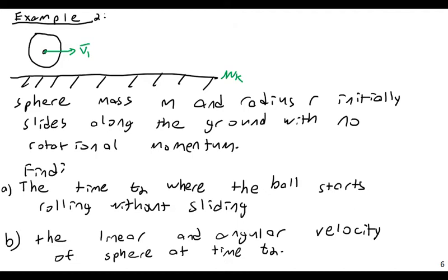Okay? So again, what is our first step going to be? Yep, we're going to draw a momentum and impulse diagram. So an initial momentum diagram, an impulse diagram, and a final momentum diagram. All right, so let's do that. And I'm going to designate the point of contact, point C. So let us consider that here.